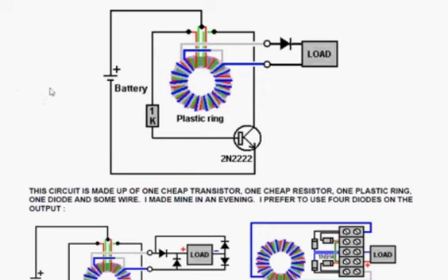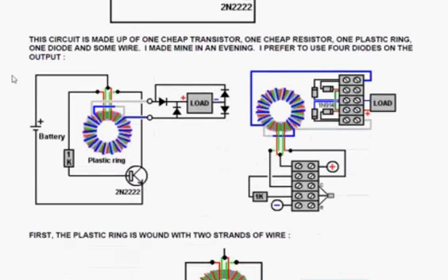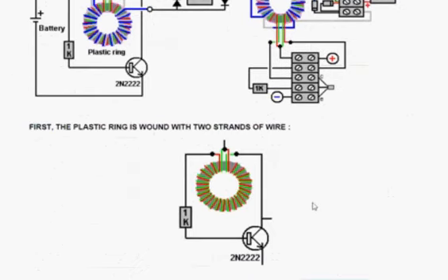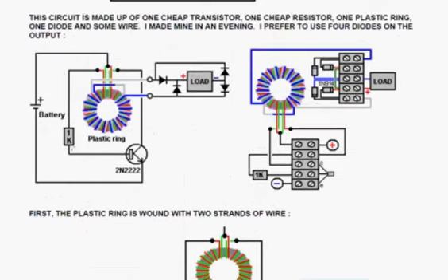And there are 2 windings on this. Both of the windings are bifilar. So initially you wind all the way around the toroid with 2 strands, and then you connect it the standard way for a Joule thief. This is a typical Joule thief arrangement. But then you wind a second layer round in a bifilar winding. This is the layer that's shown in gray and blue if you're not colorblind. And about 30% of men are colorblind.